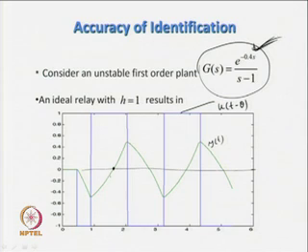Let me start my analysis from the first zero crossing over here. This time is t equal to 0, and we see that at time t equal to theta, a peak amplitude or peak output occurs. This would be the half period, t equal to Pu by 2. If I look at the plot, my peak amplitude is obtained here at time t equal to theta, which is nothing but Ap equal to y(theta) equal to x(theta).